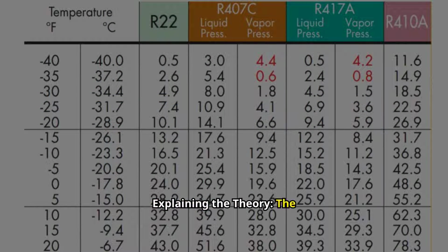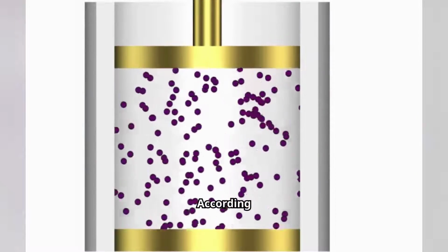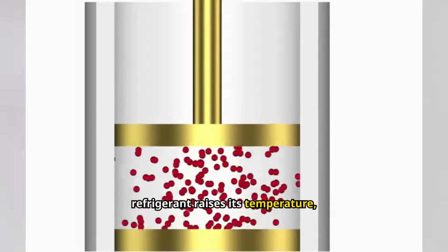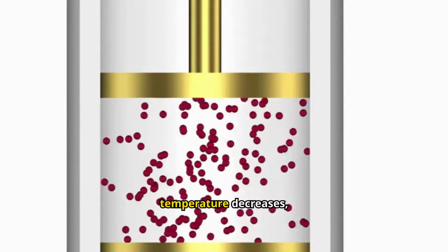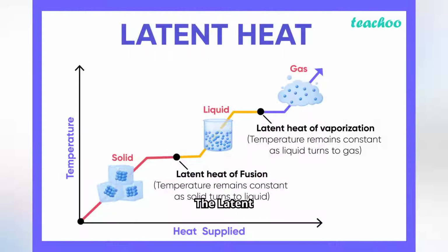Explaining the theory. The pressure-temperature relationship. The refrigeration cycle hinges on the principles of the ideal gas law and the latent heat of vaporization. According to the ideal gas law, increasing the pressure of the refrigerant raises its temperature, allowing it to release heat in the condenser. Conversely, when the pressure drops in the expansion valve, the temperature decreases, enabling the refrigerant to absorb heat in the evaporator. The latent heat of vaporization plays a crucial role during the refrigerant's phase changes, ensuring efficient heat transfer throughout the cycle.